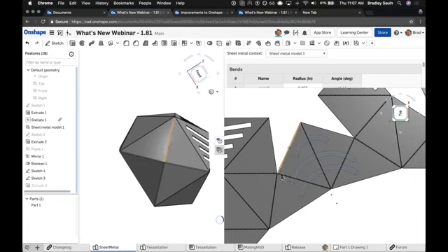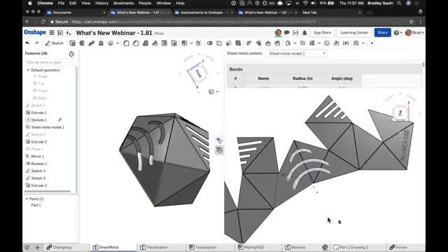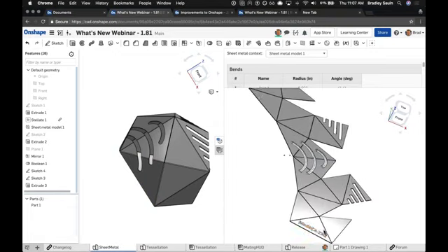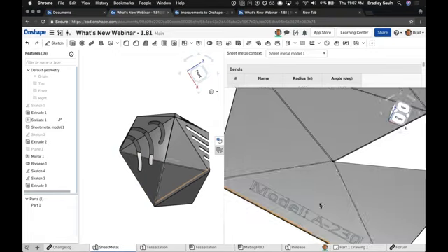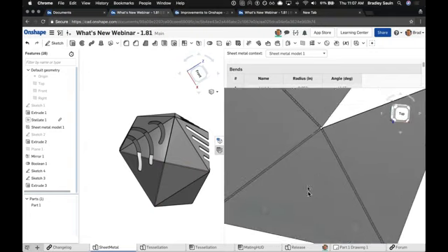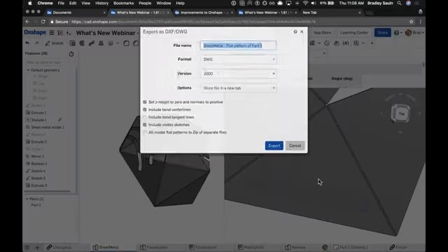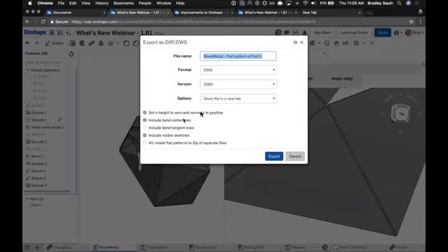Now the second side of our improvements to sheet metal, again, is the ability to add sketches to the sheet metal face. So here I put a model number on this component. I could have this configured or add a variable in here to drive this. When I right click and export out this flat pattern now, I can choose to include all visible sketches.